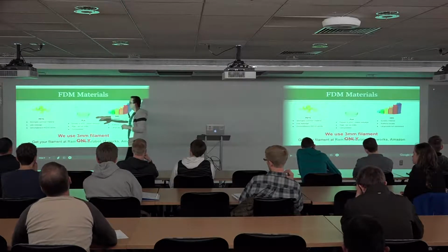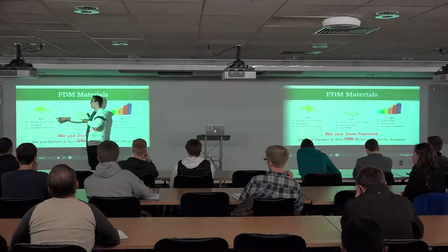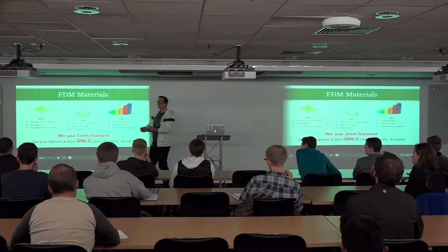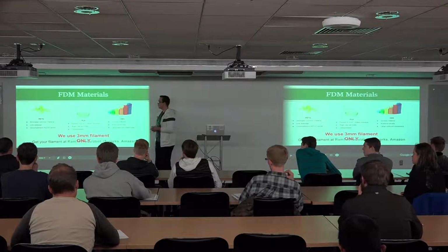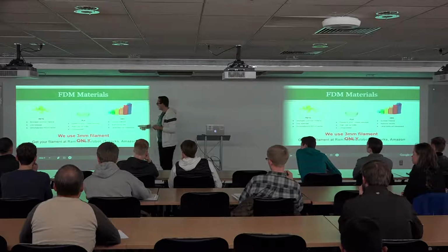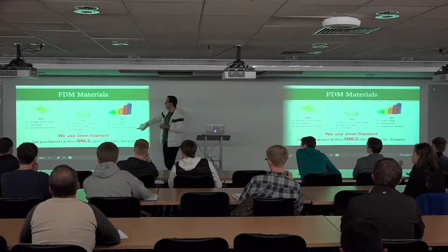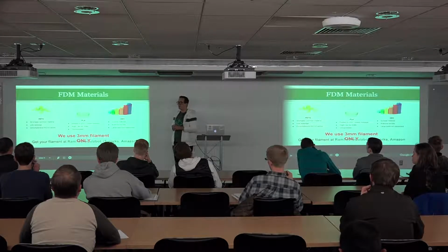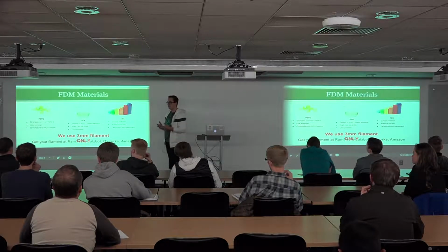Yeah, and it also has a lower warpage. So what I mentioned about the castle, I think this castle was printed with PETG. And the details came out nicely, and it didn't warp up too much while it was printing. ABS is notorious for having warpage with larger parts like that. And that print took about, what was it? Was it over 48 hours?